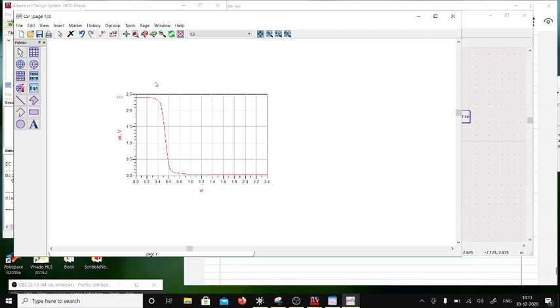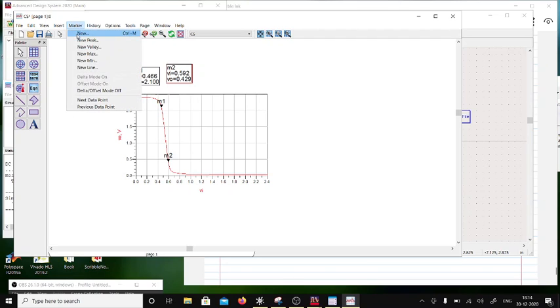Now you see that there is a gain. The slope is the gain, but the gain is negative. That's what a common source amplifier does, a negative gain, and I'll come to what that negative gain is. I'll put a marker here. This is more or less like an inverter. A new marker over here. I will also put one marker at the center. The center happens at 2.4, so 1.2 volts. At the center of the transition I am at 1.2 volts, which means the input is 0.537.